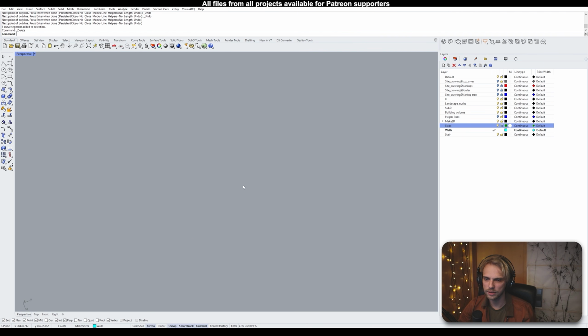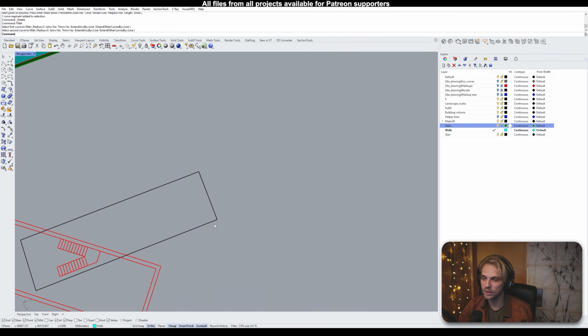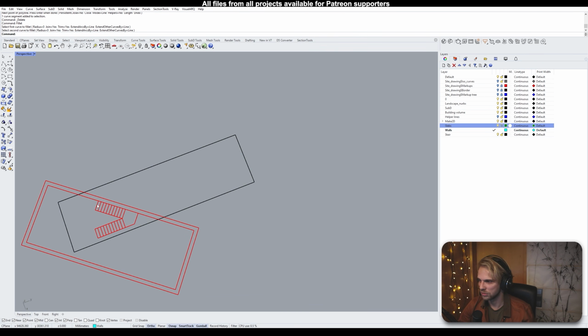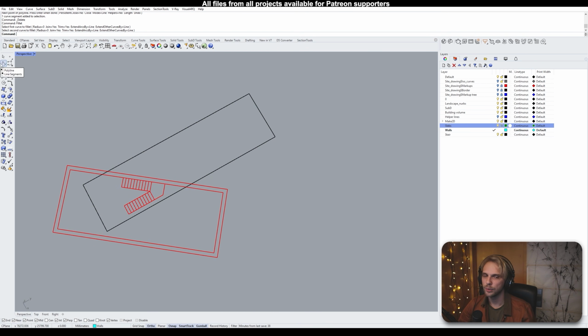Yeah, that was just a 10 millimeter fillet that I did earlier on while drawing. Always when you fillet two curves, always check if the radius is 0, or else it's going to make a very small arc that you will have troubles with redrawing later on, just as I did right now. Anyway, I have myself the outline that I need to draw.